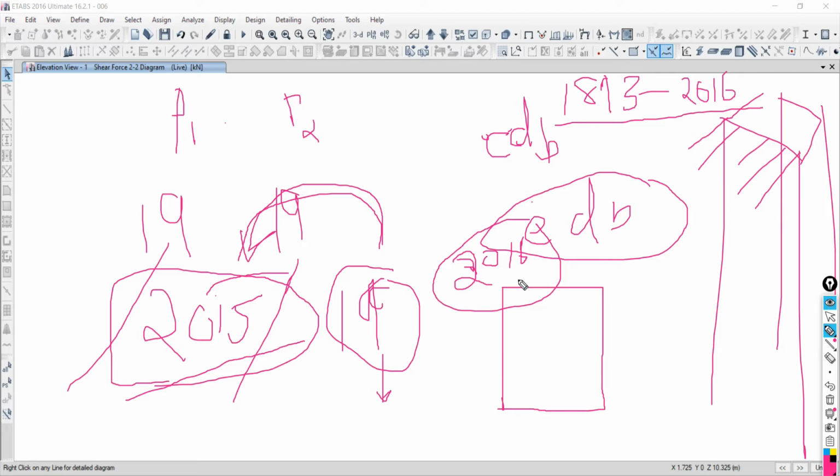No, sir. So what will happen when you are trying to open a higher version in the lower one? It will open the file. But while opening, it asks that earthquake load has been assigned by the 2016 code, so it will be rejected. If you say yes, then it will proceed. So all the assignment due to the 2016 version will be discarded in the 2015 opened file. Getting or not?